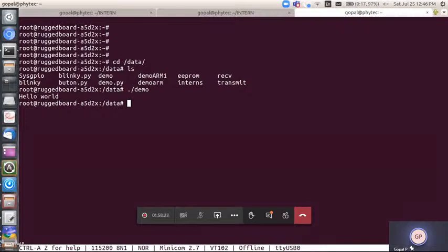My dear guys, I can tell you three options here. Through an SD card, we can do it straight away. It's the basic level: just copy your binary from your host through the SD card, plug it into your board, and you can access it. But if you keep repeating this, it becomes a burden to keep plugging the SD card in and out.